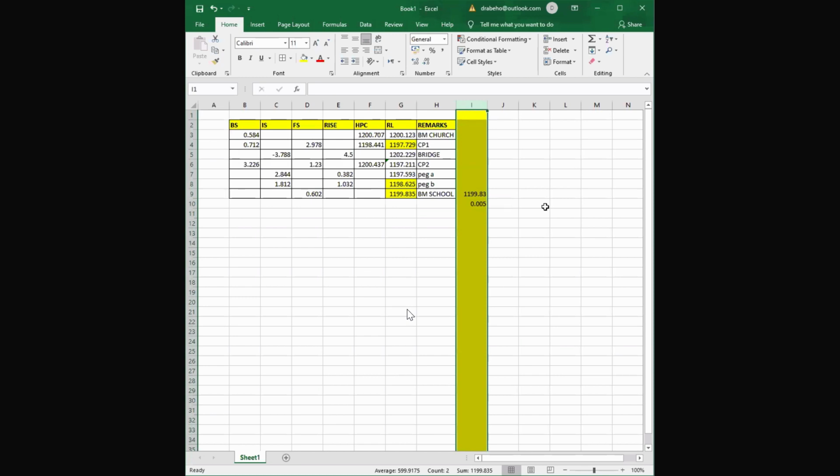In the next class, we'll see how to distribute that correction, but also how to check if we are within allowable or beyond. If, for example, the requirement in your terms of reference is that you fix your height to 2 millimeters, this is 5, you're clearly beyond the allowable. So you dismantle and re-observe until you have the required.